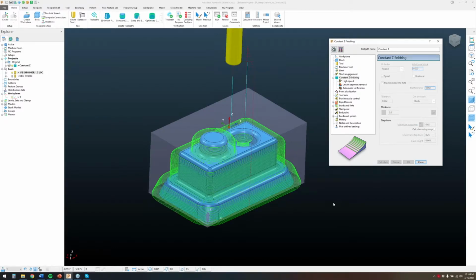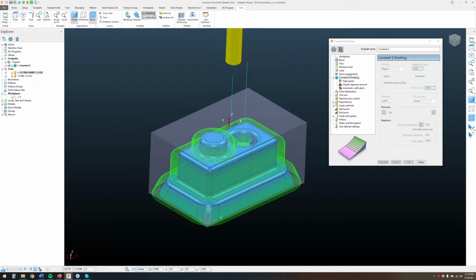You can see right now that we're utilizing the work plane that we have. I'm actually going to turn off my transform work plane because that gets kind of annoying to me. You can see that it's machining the majority of just the walls. Partially it's going to take over those fillets on the top edge, but for the most part, it's just tackling the walls of this part.